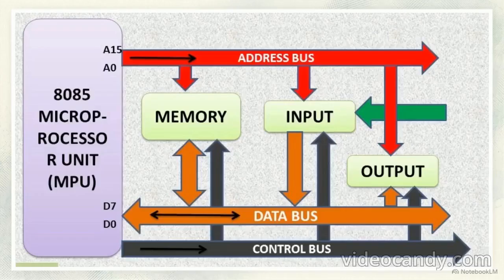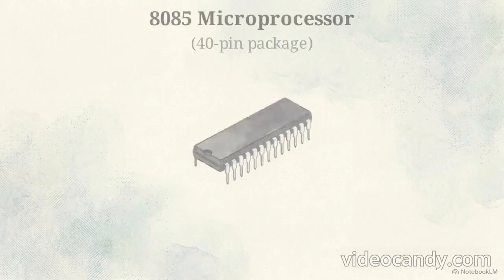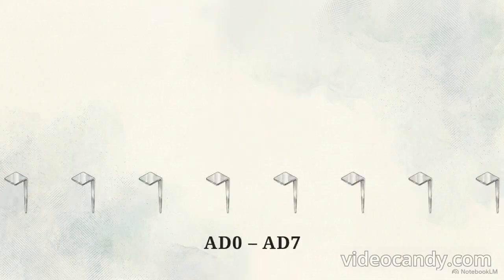This requires a physical communication infrastructure known as the system bus. This diagram traces the tripartite bus structure. The 8085 uses 3 distinct paths to interact externally. The first is the 16-bit unidirectional address bus, allowing the processor to address over 65,000 distinct memory bytes. The second path is the 8-bit bidirectional data bus, allowing binary data to flow between the processor and external devices. The third is the control bus, using single-bit synchronization signals to notify hardware of the processor state.